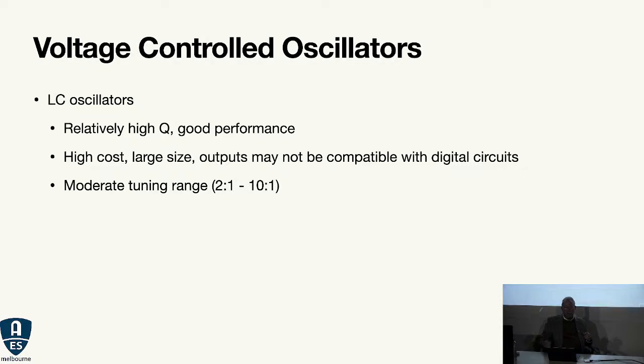And they have a moderate range. They can tune, most will do 2 to 1, in other words, from the lowest frequency to the highest. It's possible to get them pushed up to 10 to 1. Those might not be very good in terms of phase noise, but it's a moderate sort of tuning range.